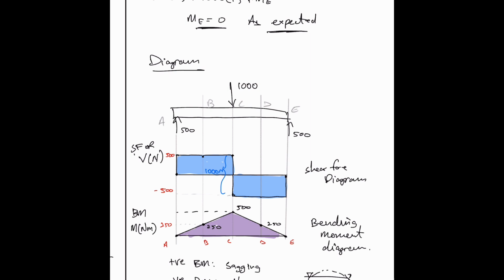And again, another advantage of the bending moment diagram is that you could see where it's positive and where it's negative. So you could have an idea, by just looking at this diagram, how a beam will be deflected. You wouldn't know the values of deflection, but you could get a picture of what direction it's going to deflect in.